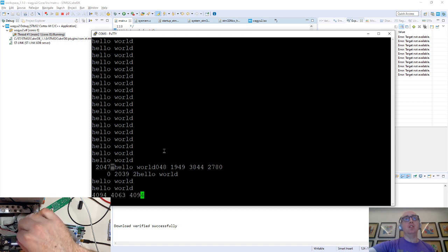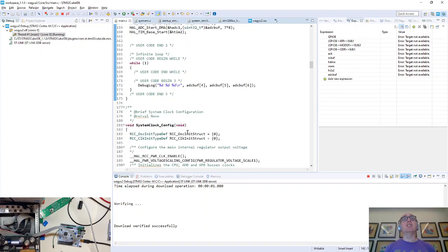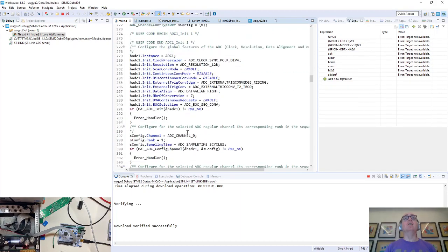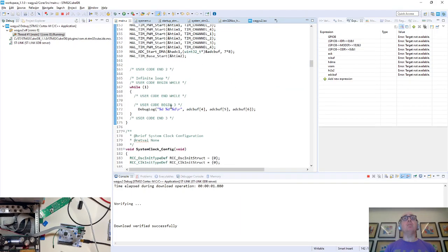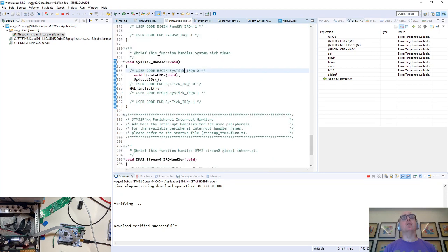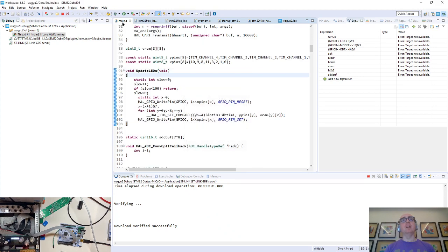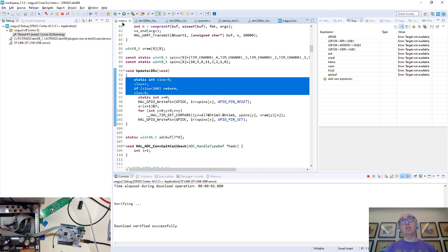So we have successfully hooked up 7 ADC pins, including the last 3 of which we were sending to the TTY, which I think is a big success. Let's use it to animate our display a little bit more excitingly. That VRAM buffer that I created ages ago: in our callback called update LEDs, I've got the thing that's basically slowing it down, so we can sod that off.